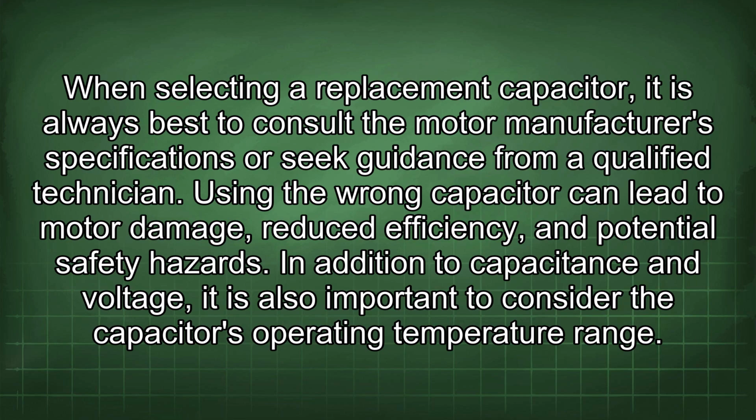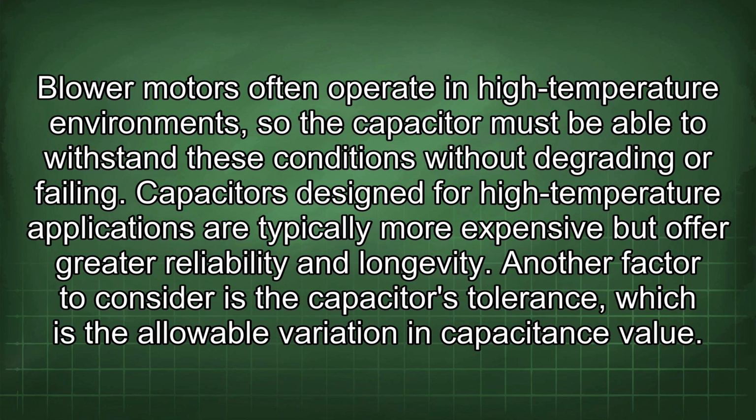In addition to capacitance and voltage, it is also important to consider the capacitor's operating temperature range. Blower motors often operate in high-temperature environments, so the capacitor must be able to withstand these conditions without degrading or failing. Capacitors designed for high-temperature applications are typically more expensive but offer greater reliability and longevity.